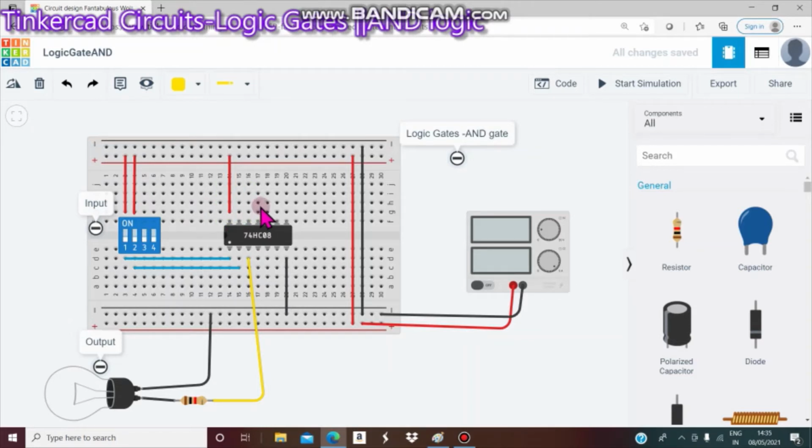The fourth step is the lamp connection. The lamp is an output device. That is why we connect it to the integrated circuit's output. Now connect the lamp terminal 2 or terminal 1 to the bottom layer of the breadboard, the breadboard's bottom minus. Then from the breadboard's bottom minus you connect a wire to the integrated circuit's ground.